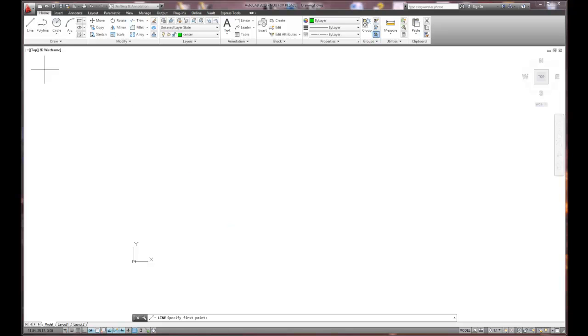I picked the line command, and from math we learned that it takes 2 points to draw a line. So if I left mouse click a point and move it over, notice that it tells me the size of the line, the angle that I'm working in, all the basic details. What if I typed in a distance of 3? Or in this case it's really far, so let's go ahead and type in a distance of 8. I can literally type in a distance of 8, hit the enter key. You'll notice that I've got center lines and they're green. Not the best color for a white background.